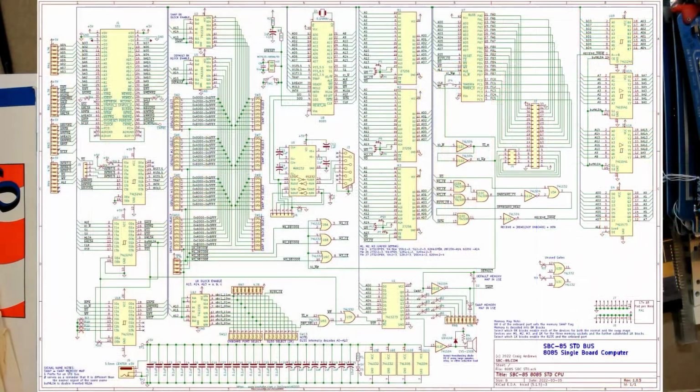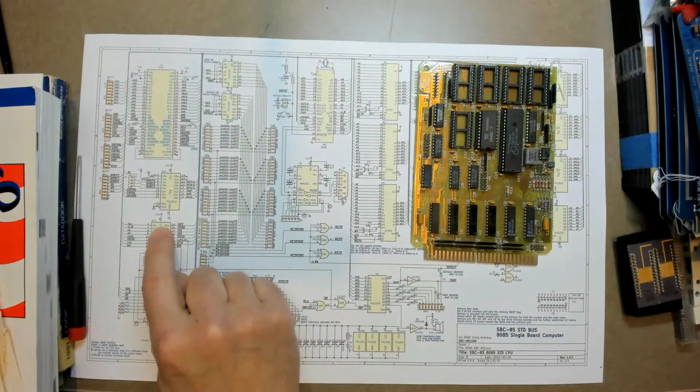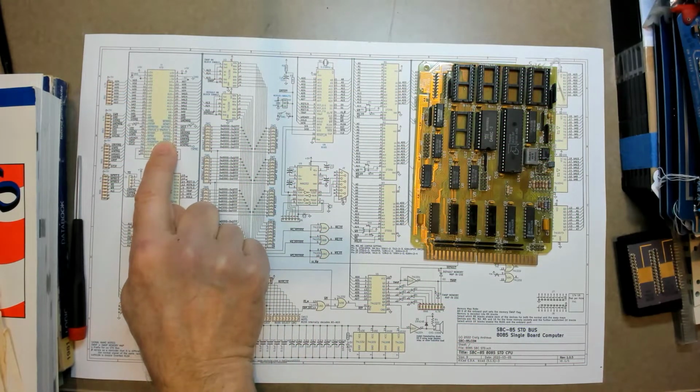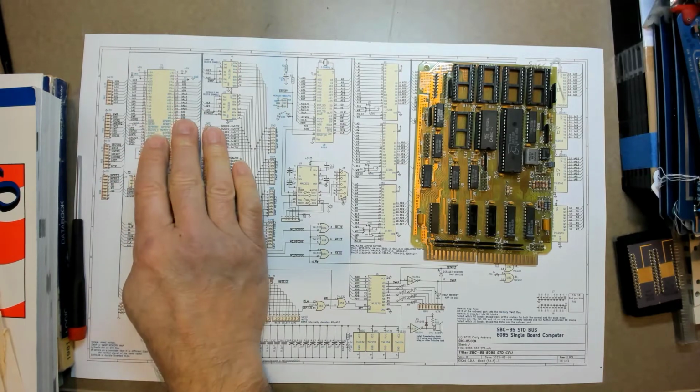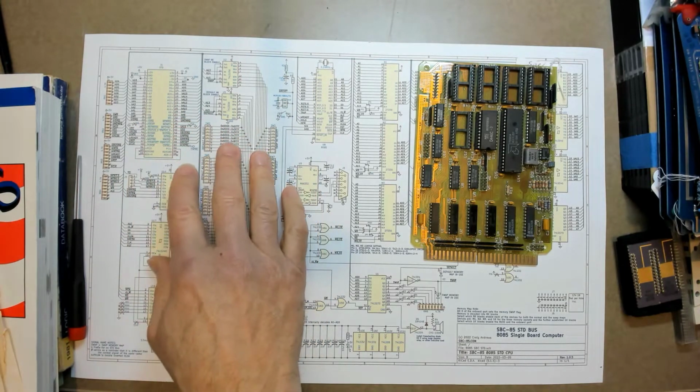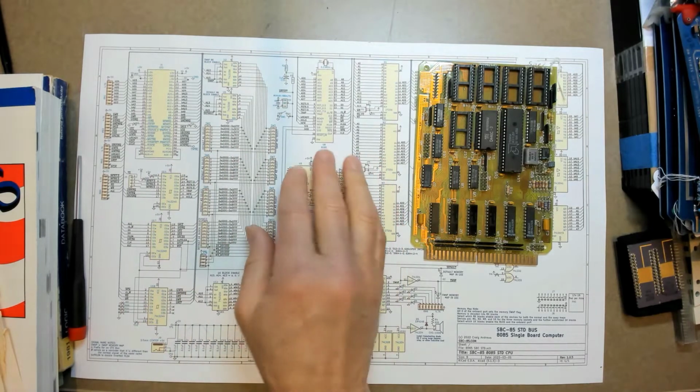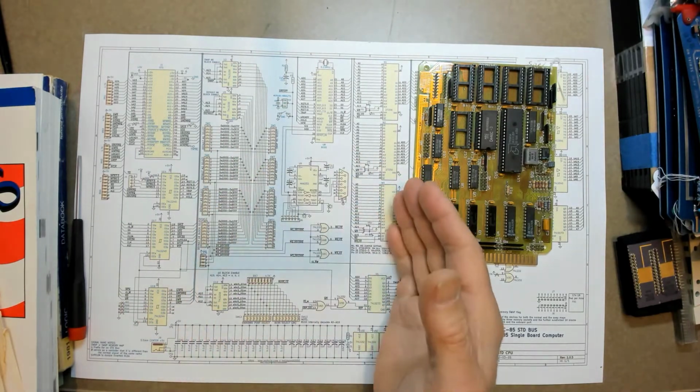The first thing to note, and this is key to being STD bus compliant and allowing DMA, is that the STD processor bus master must be able to relinquish the bus to other cards whenever they request it. So when this primary card relinquishes the bus, it's available for use by other cards, for example, to do direct memory access, or DMA, say from a floppy controller to a RAM card.